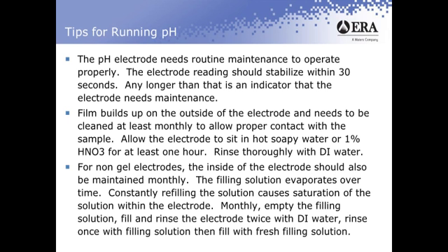So what you're going to notice is you're going to take your filling solution, fill that up to the line, up to that little hole on the side of the electrode, and then it's going to evaporate. And then you're going to fill more solution in there, and it's going to evaporate. What happens over time is that you're going to get saturation of the solution that's in there. The saturation really hurts the salt bridge that's in there, and it doesn't really allow for proper contact of the sample with the electrode.